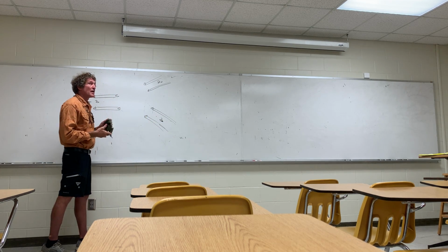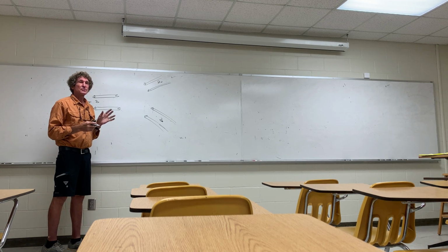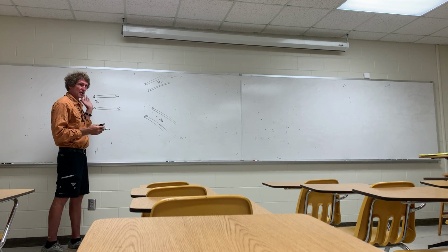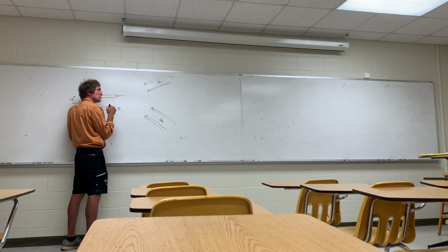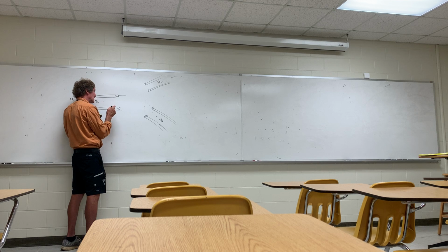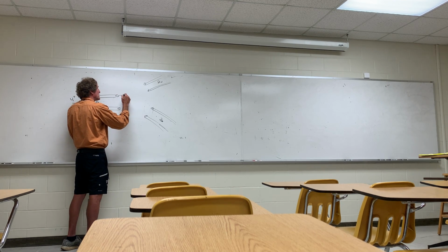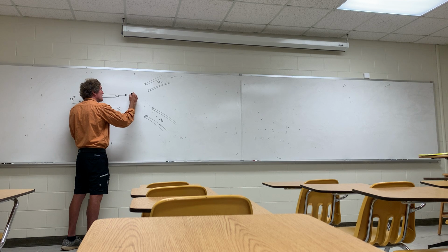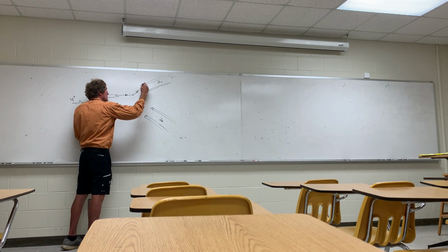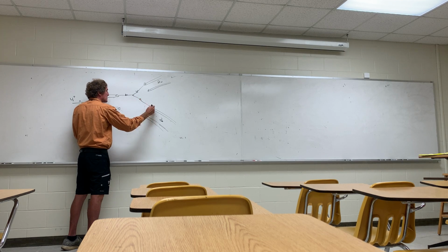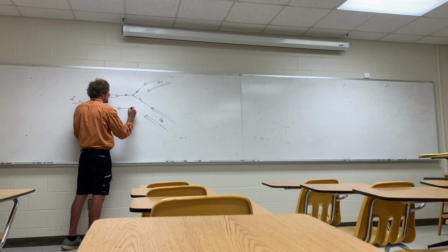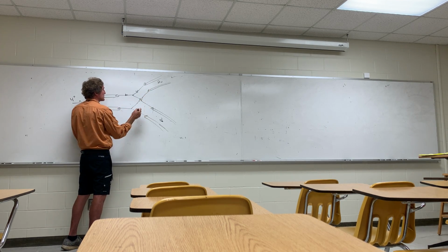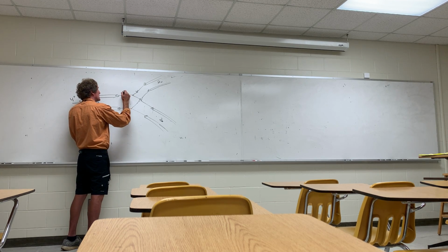So now my primary goal is to make sure there's no reflected energy. That's the primary. Can everybody follow me on that? So how do I do it? Well, what they usually do, because it's split 2 ways, 1 way coming in, split 2 ways coming out, they're going to add a small resistor here, and a small resistor here, and then a small resistor here, and they're going to have, this will be the same ground plane, so connect there, and then up here. So they're going to have 3 resistors in this triangular fashion.